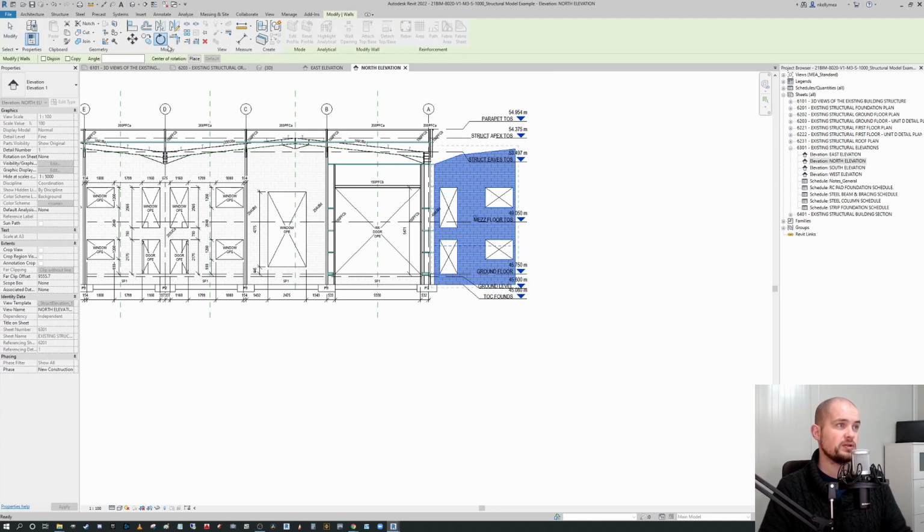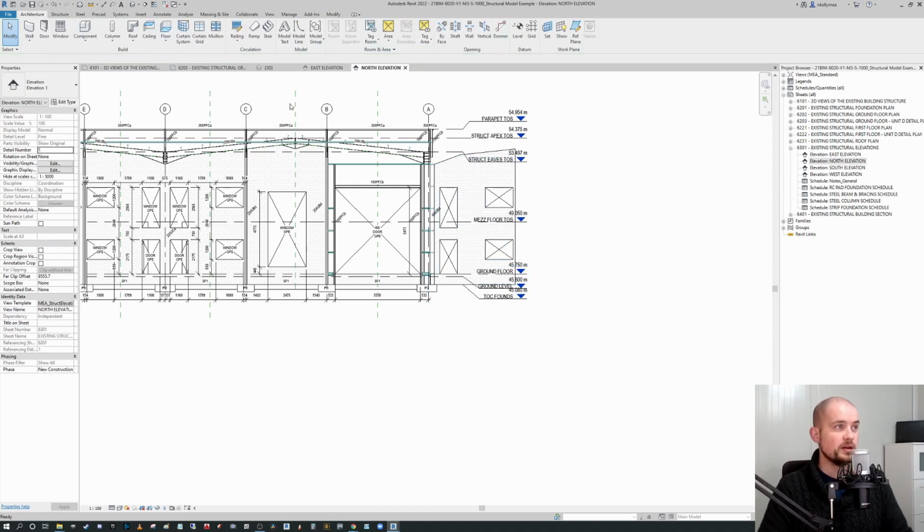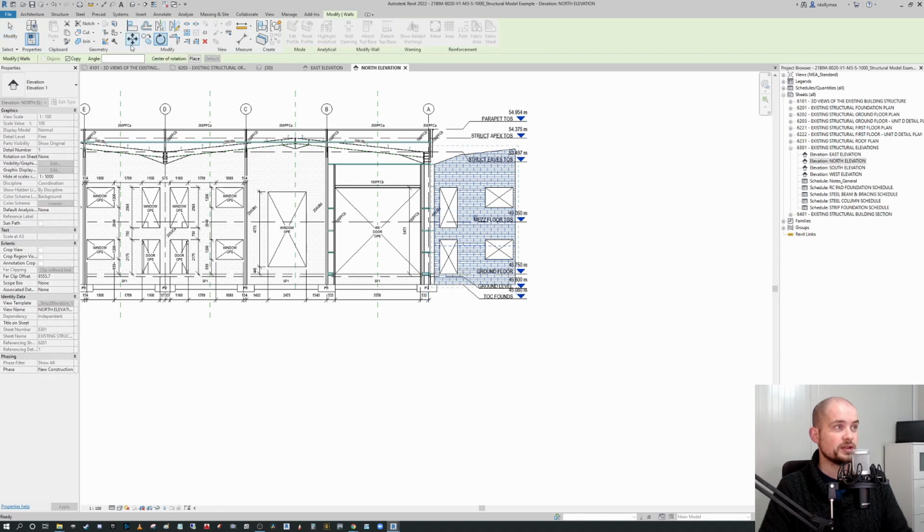Similarly, the rotate tool, for example, and this is a bad example of a tool to use rotate, but the copy or disjoin will be retained. So that's obviously not going to copy it now, but if I select that again and I go to rotate, you can see that copy remains selected because I used it previously. And again, when the models are shut down and Revit itself is shut down, it will retain the actual tool set and how you used it, the settings particular to the tool set.